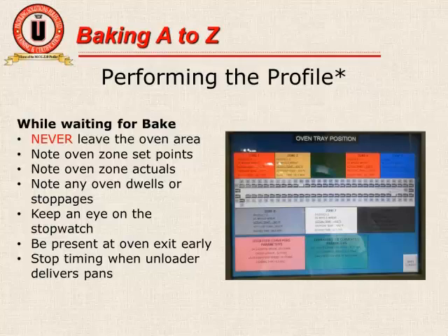It may be that the conveyor's speed is not correct because of calibration issues. You want to get a good read on how long that bake time is compared to what it was set for. It's possible the oven needs calibration or adjustment.